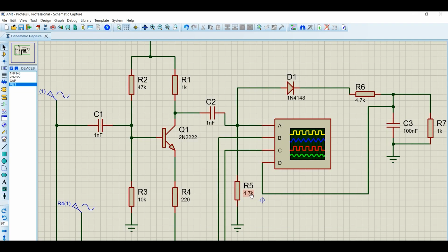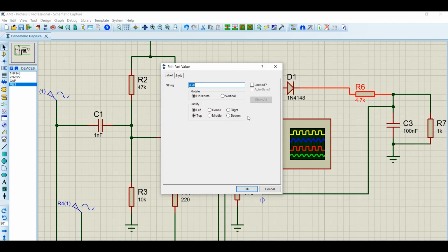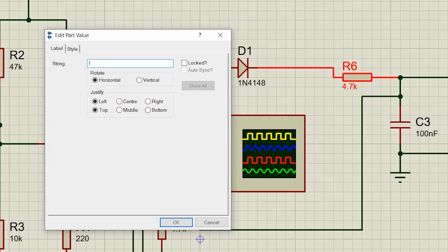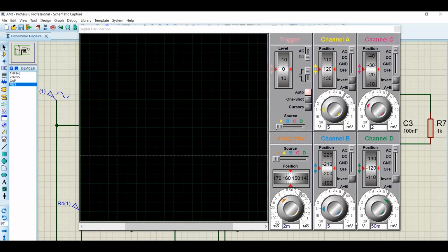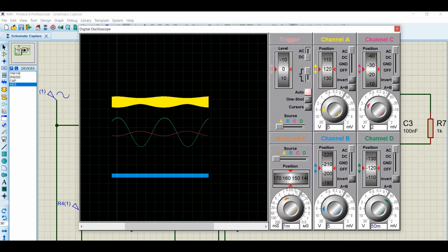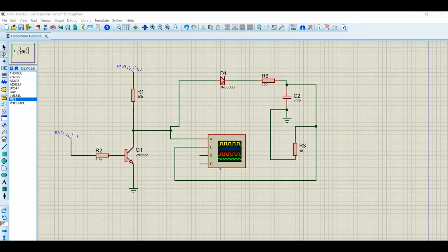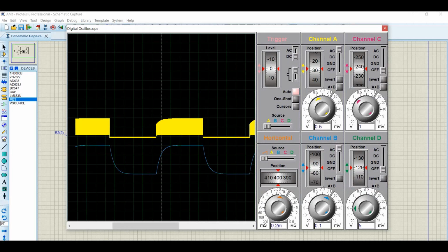That's because we forgot about impedance matching. On the modulator side, these two resistors are in parallel, which means the output impedance of the circuit equals the smaller resistor, which is 1 kilo ohm. So all we have to do is change the input resistor to 1 kilo ohm as well. And that's it. Oh, by the way, the same method works for demodulating ASK signals too.